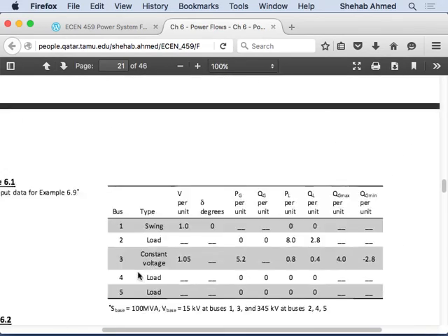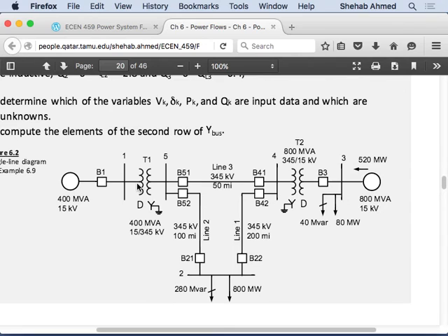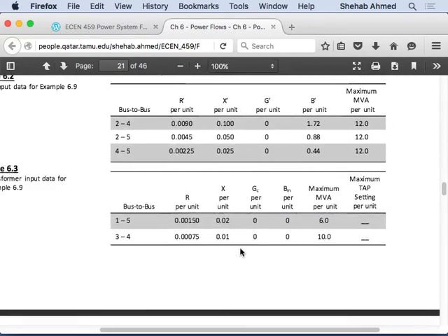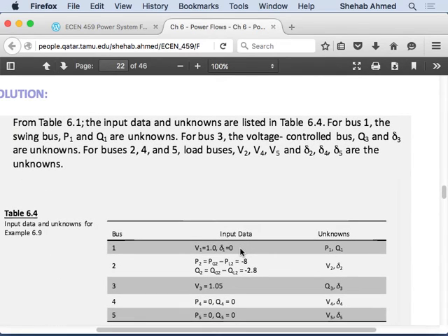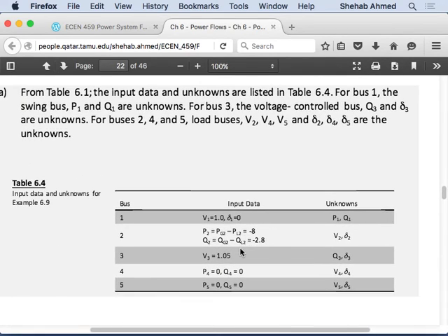So now you have everything. You have all the admittances between buses, based on your knowledge of the transformers and the transmission lines, right? So now you can start constructing your system. You go through your buses. At bus 1, it's a slack bus. I know